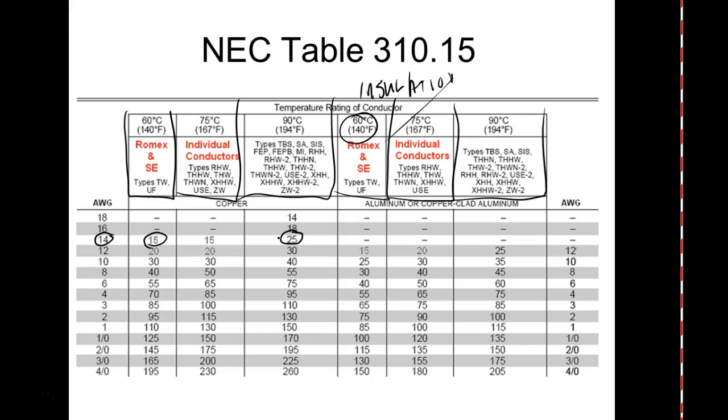So that means if my conductor's not over 100 feet, then I can run this wire in any situation that we would run into in a residential situation and not exceed the ampacity of the conductor. When you say derate, it's basically reduced by. So if you looked at the code, when you get into commercial wiring, you start figuring out how much you have to derate it for different types of situations.